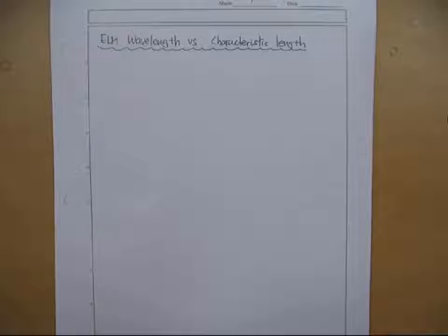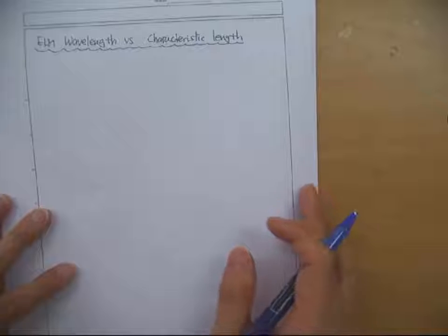Today we'll talk about how we measure the soil's electromagnetic property, and mainly we'll talk about the electrical property, so the permittivity and the electrical conductivity. Do you remember the scattering in the mechanical wave? When your wavelength is similar to the scale of the particle, the wave will feel that you have an interface, so the wave can reflect or transmit depending on the impedance mismatch, right? Impedance ratio. That can be applied to the electromagnetic wave too.